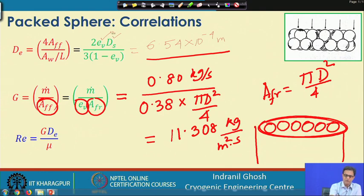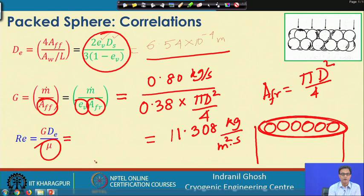We have the value of the equivalent diameter, we have the value of G, and what we need to know is the viscosity of the fluid. The fluid is nitrogen at an average temperature of 200 Kelvin, and its pressure is already known. At that temperature and pressure, we have to evaluate the properties of nitrogen, and mu will come out to be 12.95.